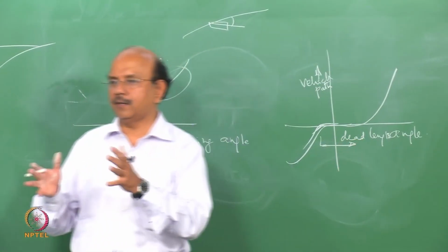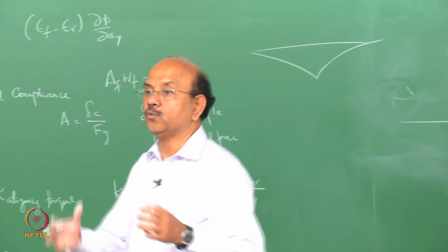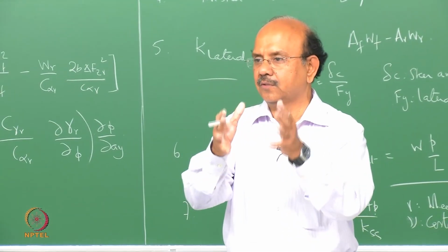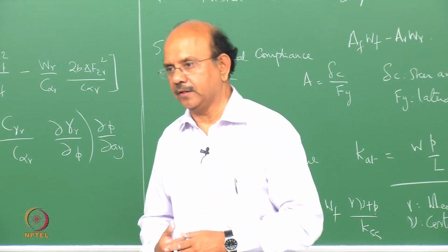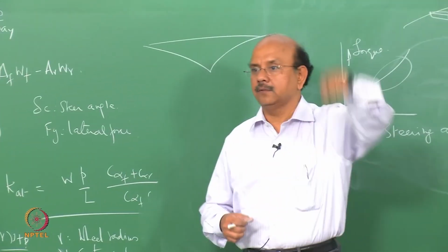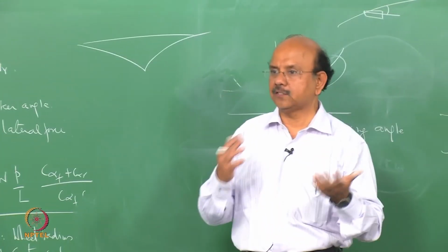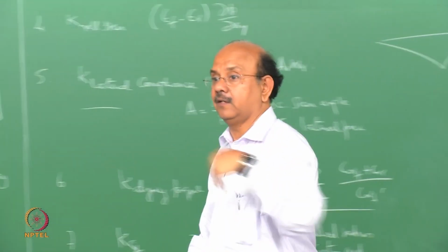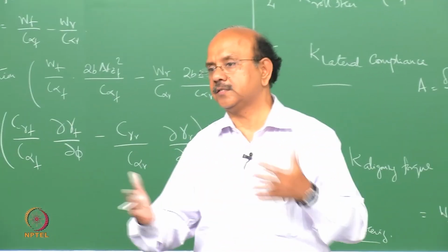So a very small value, because you would see how much the steering actually changes when you go straight. When you turn, the steering angles are so high. The ratio, for example, between the steering wheel and the road wheel may be in the order of 30s.